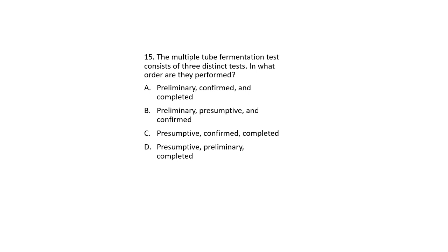If the gas is present after 48 hours in the incubator, that means you have coliform. So for the confirmed test, they will take the positive samples and move them to another sugar solution that's filled with brilliant green bile, which apparently only coliform will produce CO2 in. It's more selective for what bacteria there is. 48 hours again, if there is a gas, you're positive for coliform.